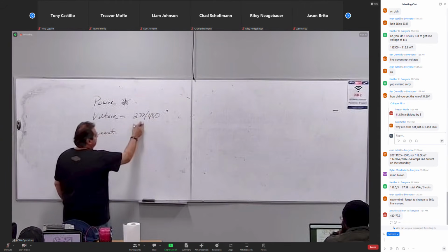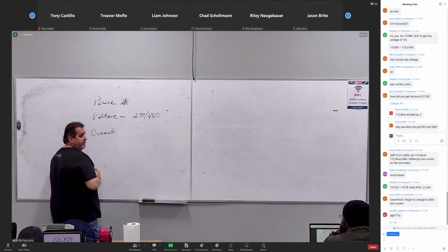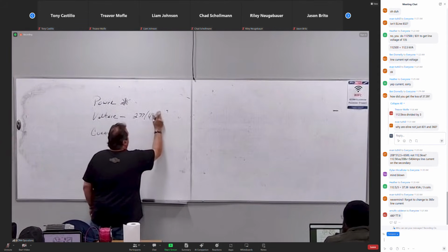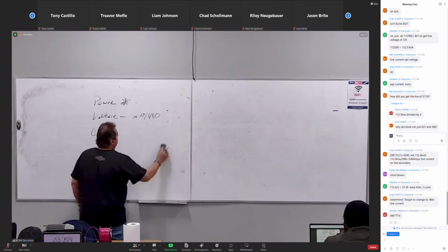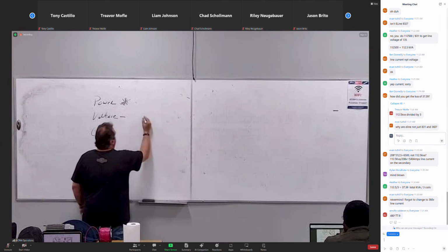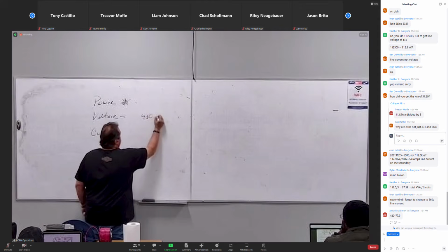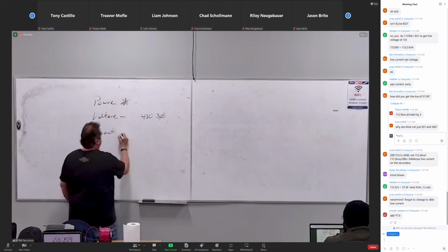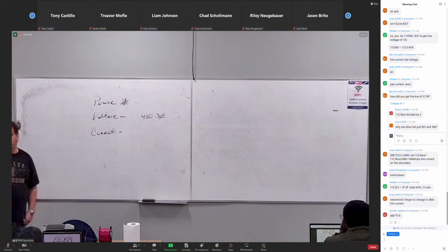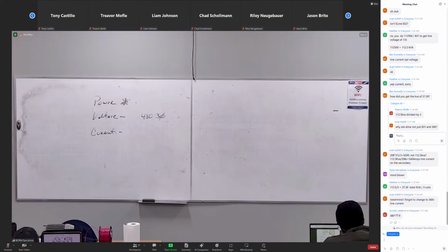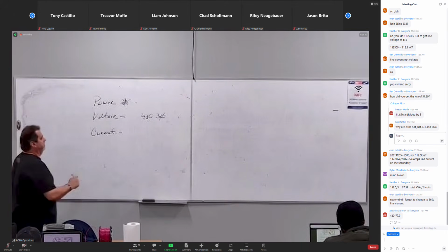Okay, cool. So I'm shipping 480 volts to my load, right? It's a 3-phase load. Agreed? So it's going to be 480 volt 3-phase, correct? Coming from a Y, which is 480 volts, 3-phase. Do I have a current? I do, right? 45.8. Isn't that my line current?